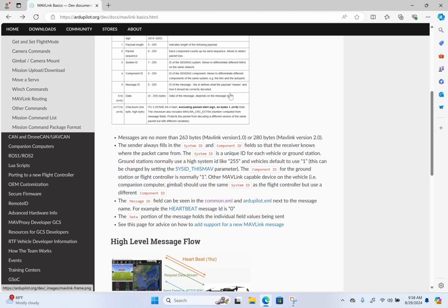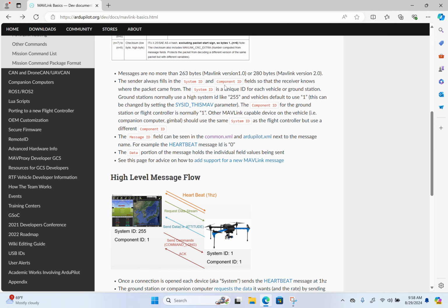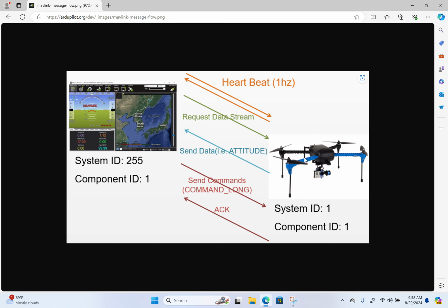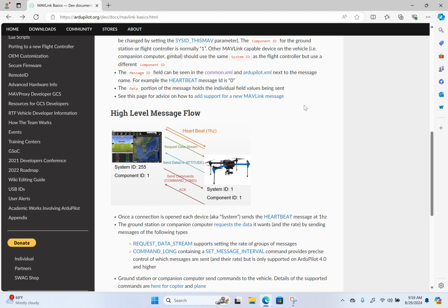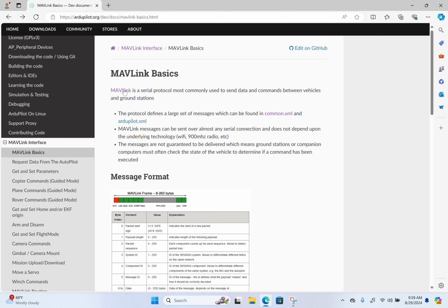So how do we do that? Well, we have to have the flight controller. There are these arrows. There has to be some way of sending bit data, okay? And actually, with Mission Planner, with a USB cable, that's exactly what we've been doing. When we connect from the computer to the flight controller with a USB cable, Mission Planner is communicating via MAVLink.